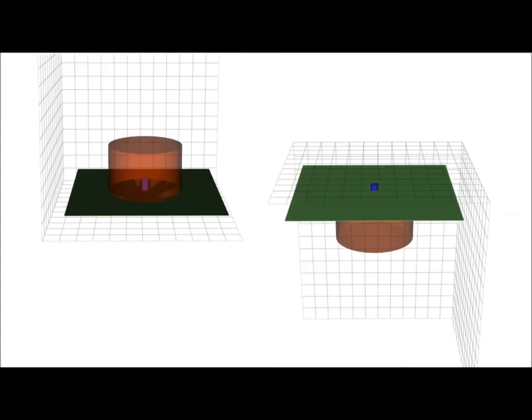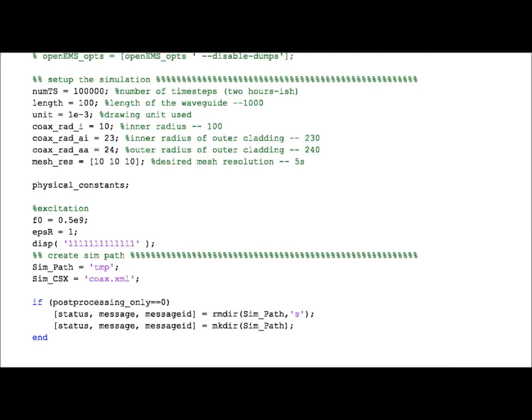As shown, the structure of a dielectric resonator antenna consists of a coaxial signal that feeds into the bottom of a cylindrical dielectric material that is mounted on a metal ground plane. As you can probably imagine, the resulting simulation will consist of 3 CAD geometries and 1 coax excitation. In the code, as per the template conventions, we initiated all of our important physical constants and variables. These parameters included the maximum number of time steps for the field simulation, as well as the necessary size dimensions, frequencies, and permittivities.